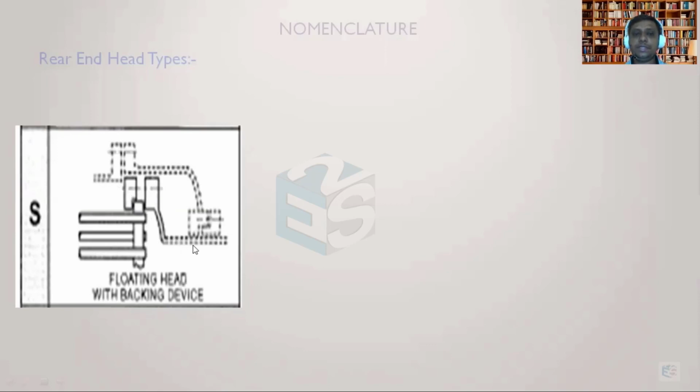So this represents your tube side. As you can see over here, the outlet has been taken from the other side. This is possible only when there is an odd number of passes. But most commonly, to avoid a sealing arrangement over here, this floating head will always come in 4, 6, 8 passes. So there will not be any nozzle taken out from this head. All the nozzles will be on the stationary side. So there will not be any problem.